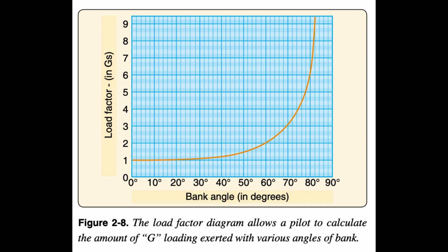Even so, under the right set of adverse circumstances, such as high-density altitude, turbulent air, high gross weight, and poor pilot technique, sufficient or excess power may not be available to maintain altitude and airspeed. Pilots must take all of these factors into consideration throughout the entire flight, from ascending to a hover to landing. Above 30 degrees of bank, the apparent increase in gross weight soars.